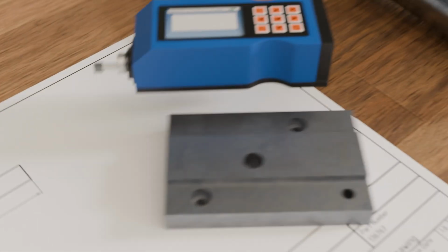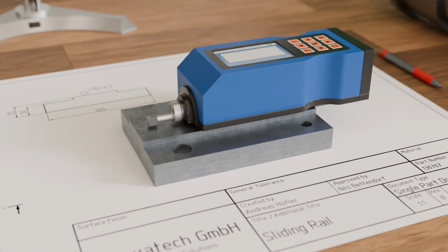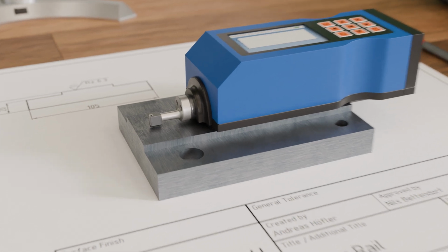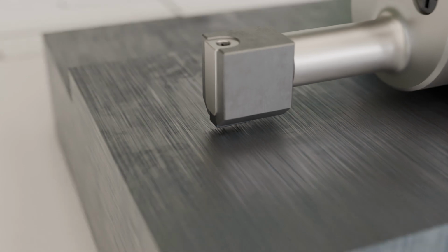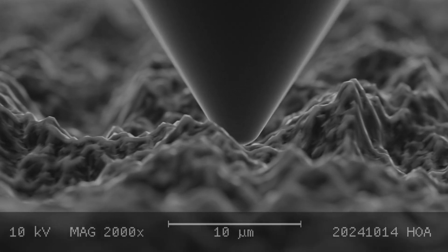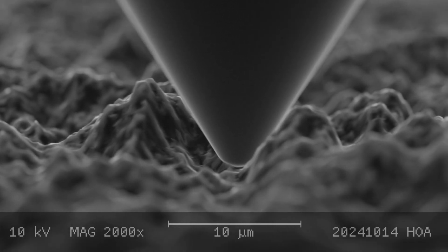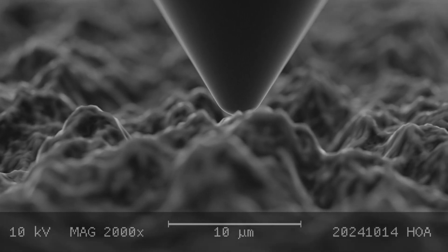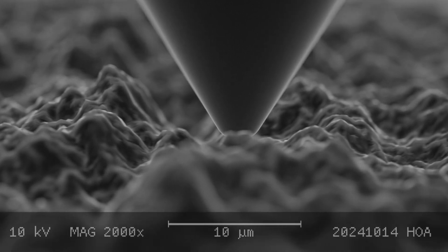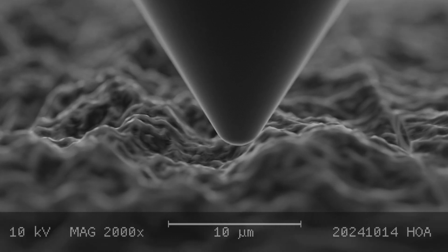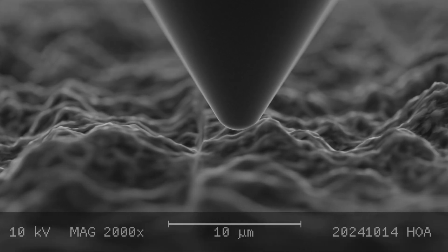In the Stylus Profiling Method, the surface of a workpiece is scanned in one direction using a very fine diamond tip. The up and down movement of the tip while scanning the surface is inductively recorded by a measurement system. The force with which the tip presses on the surface is only a few millinewtons. The stylus tip typically has a radius of 2, 5, or 10 micrometers. Essentially, roughness can only be measured as far as the stylus tip can penetrate into the structures.